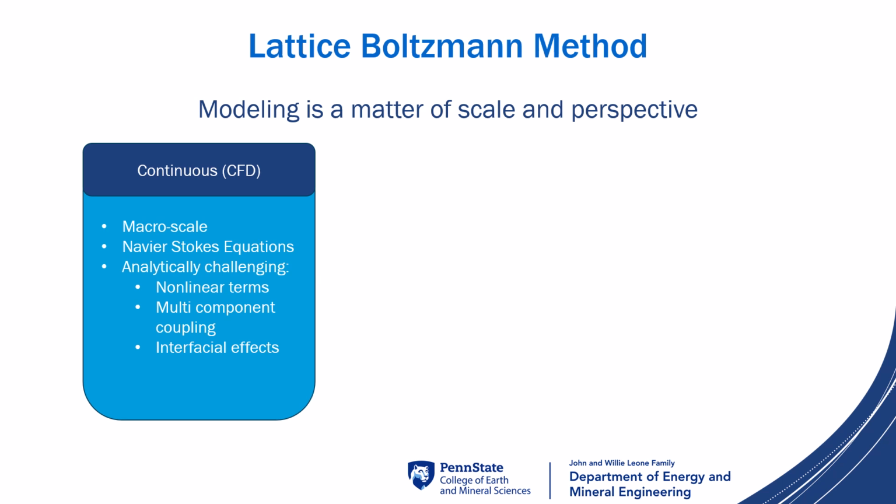Additionally, the Navier-Stokes equations are a set of coupled partial differential equations with components in the x, y, and z directions. These components are linked through the pressure and velocity fields, so solving one equation typically requires knowing the solution to the others. Finally, boundary conditions. Navier-Stokes struggles with curved and moving surfaces, and geometric complexity makes analytical solutions nearly impossible outside of ideal cases.